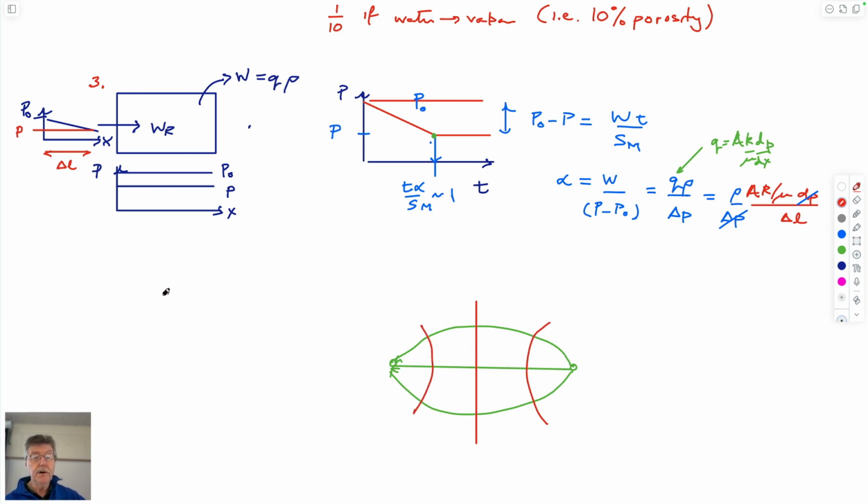I suppose we also know that you can define the volumetric flow rate as equal to the number of flow channels divided by the number of drops. These would be drop 1, drop 2, flow channel 1, flow channel 2, etc. And multiplied through by hydraulic conductivity and delta H. This is for fluid flow.